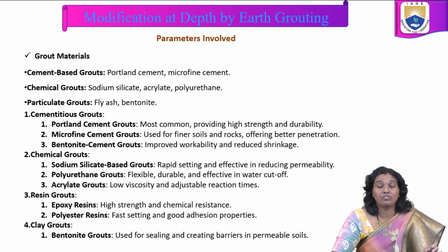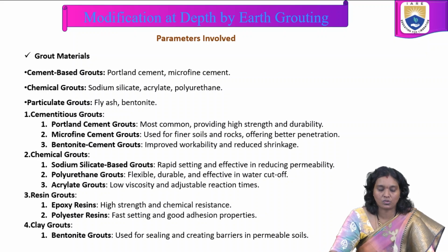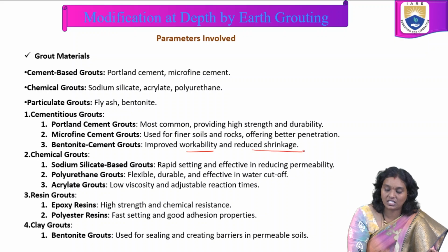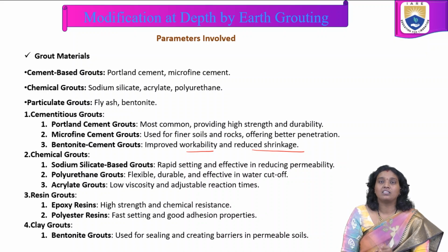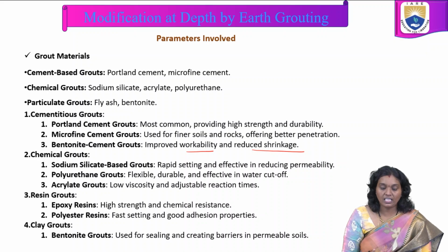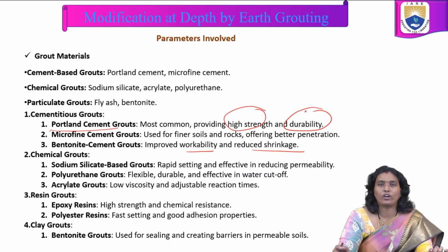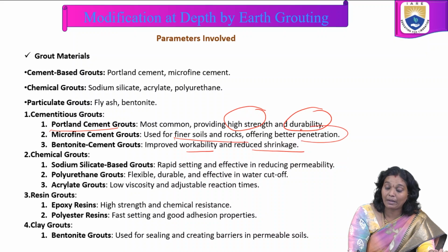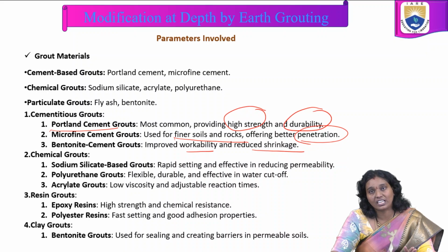Microfine cement grouts are used for finer soils and rocks, offering better penetration. Bentonite cement grouts improve workability and reduce shrinkage. Each material has its own specification, so based on the desired property we choose the grout material.